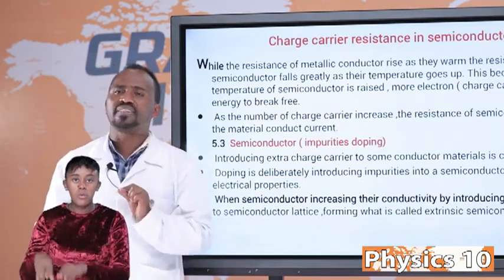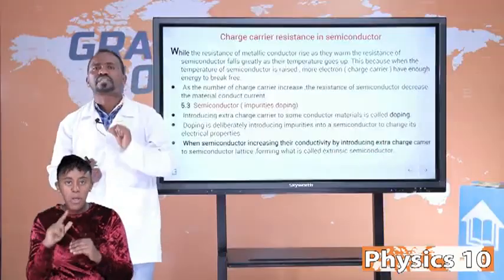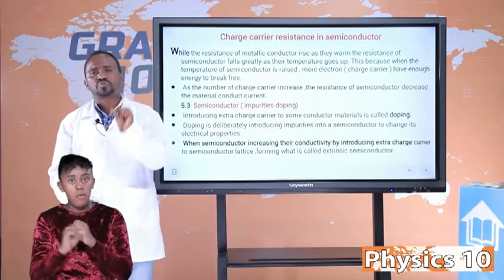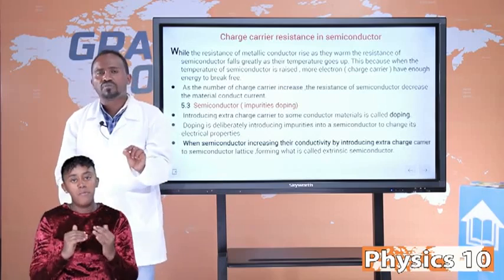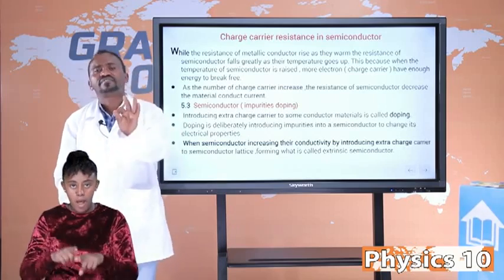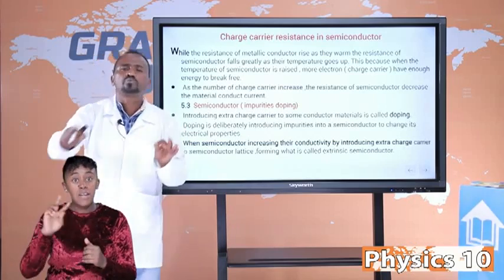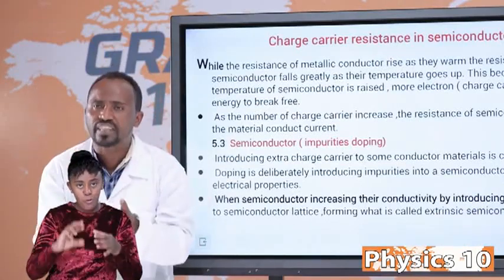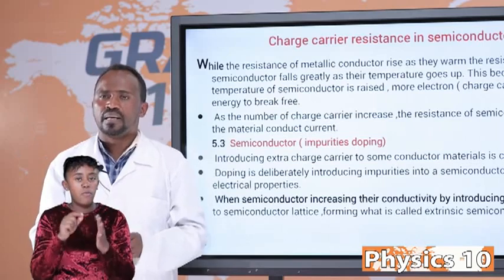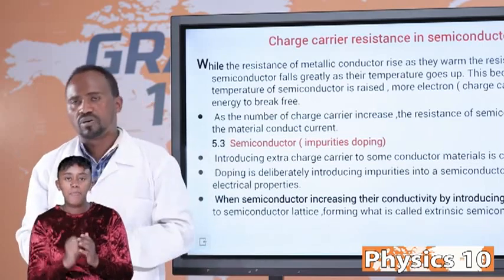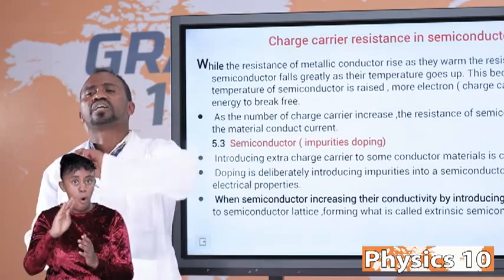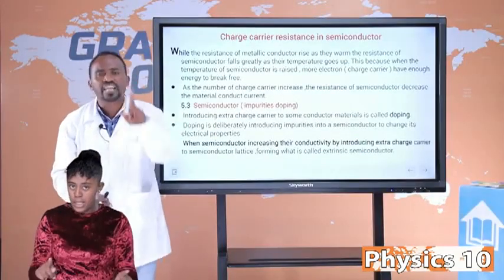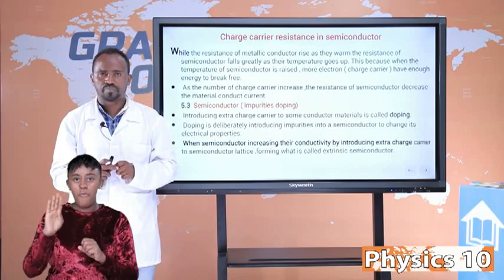Let us say some points about how a p-type semiconductor is formed. A p-type semiconductor is formed when an atom having 3 valence electrons in the outermost shell is combined with a semiconductor, for example, silicon. Take boron, for example: it has 3 valence electrons in the outermost shell, but silicon has 4 valence electrons.